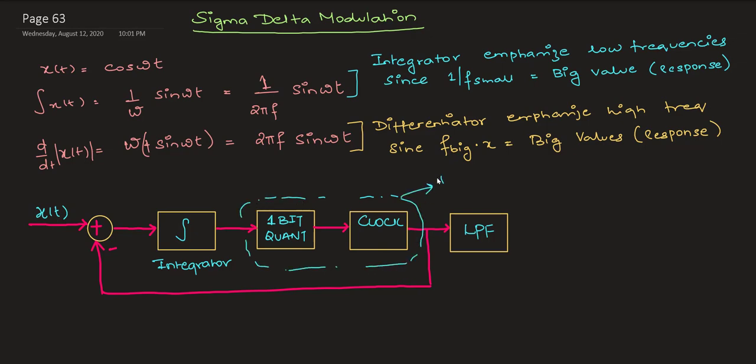In sigma delta modulation you use an LPF, or the integrator, in the encoder and also at the decoder. So you can tune your encoder LPF and decoder LPF in such a way that you get the best reconstruction output. Sigma delta modulation is an improved version of delta modulation because of the low pass filter syncing with the integrator in the encoding and decoding process. Understood?